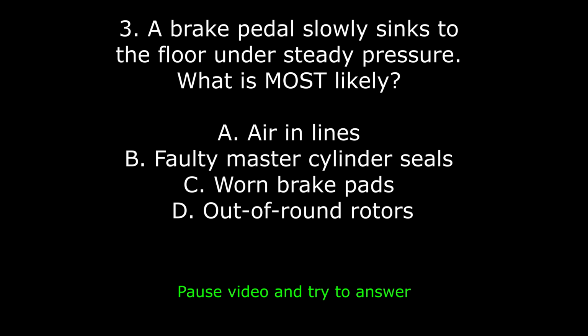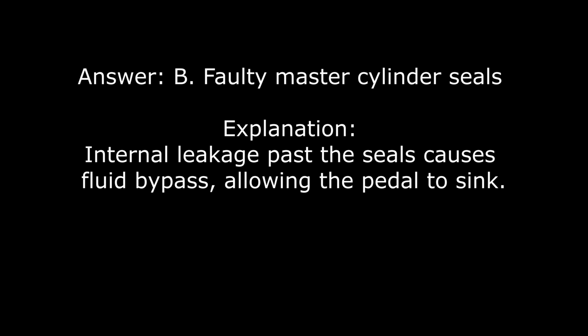3. A brake pedal slowly sinks to the floor under steady pressure. What is most likely? A. Air in lines. B. Faulty master cylinder seals. C. Worn brake pads. D. Out-of-round rotors. Answer: B. Faulty master cylinder seals. Explanation: internal leakage past the seals causes fluid bypass, allowing the pedal to sink.